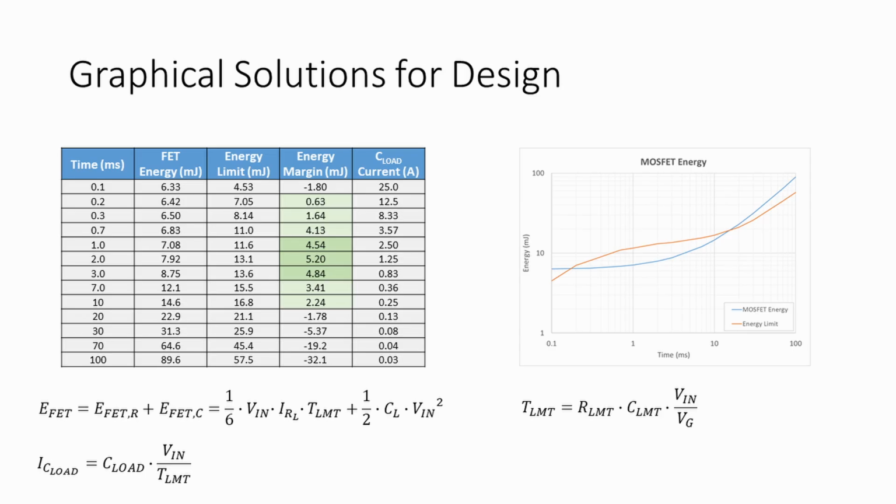So back to what we were doing, trying to figure out the output voltage rise time, or T limit. To keep the MOSFET safe, we'll use 2 milliseconds for the rise time.